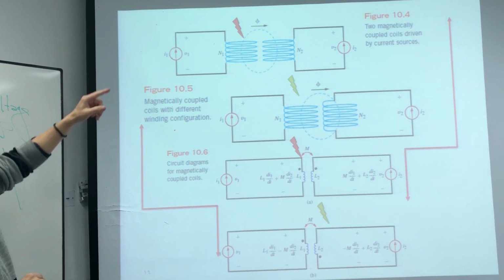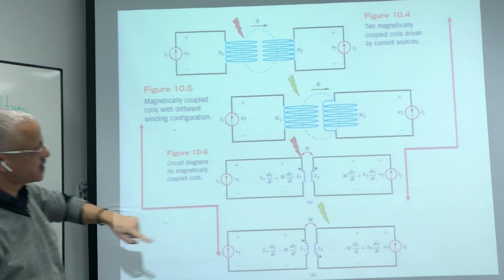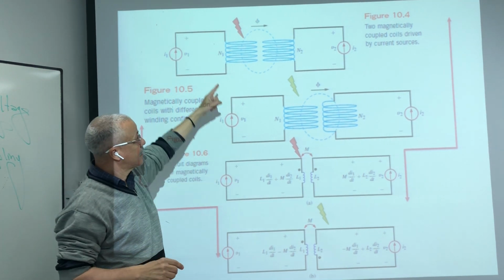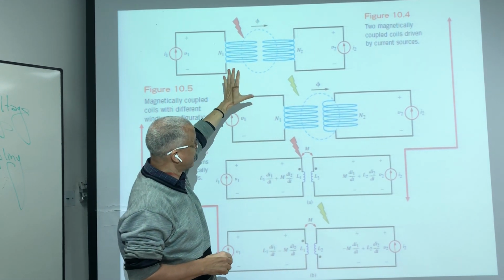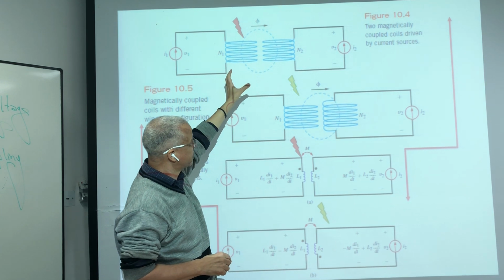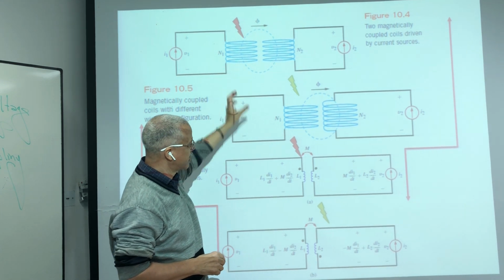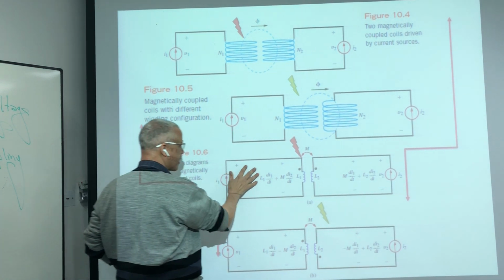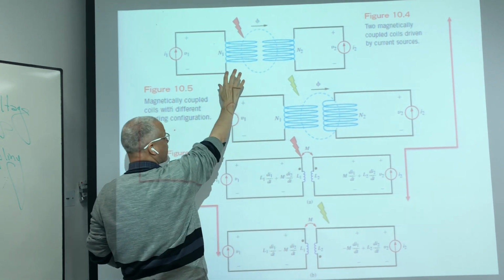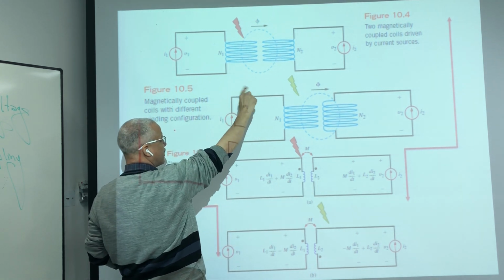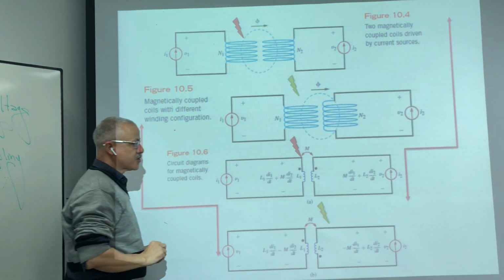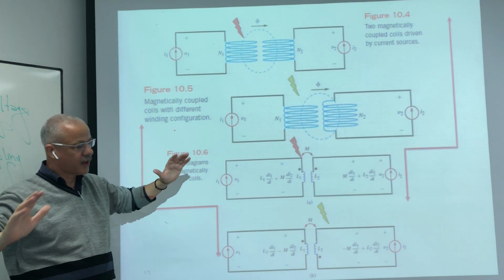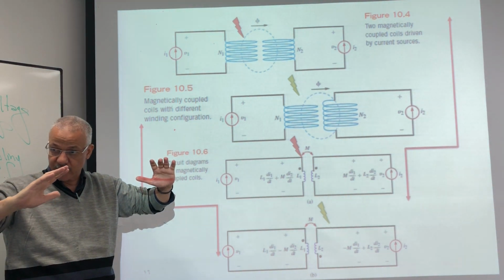So this is the reason for putting the dot. Look here, for the first circuit, we reversed the first circuit. If we reverse the first circuit, we will keep the same turns ratio in these directions. So here we have two circuits. If we have the winding like this one, we can put dots here and here. So we have the currents I1 and I2 in the same direction.